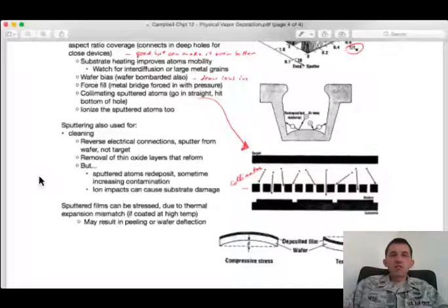And so sputtering gives you better films and is more commonly used. It's kind of taking over the industry. But even so, there are better parameters than others. I have here a figure from Campbell where you can see the quality of the coating, whether it's porous or, I guess this one would be cracks. There's an optimal combination of temperature and pressure that gives you the best coating. So just like in anything else, you can tune it to have better results.